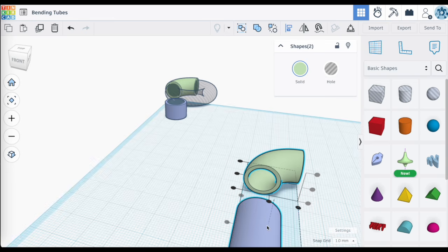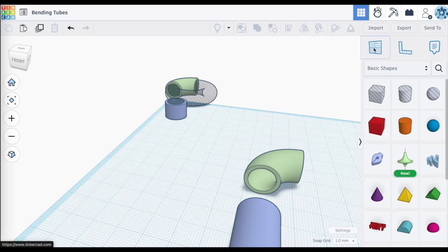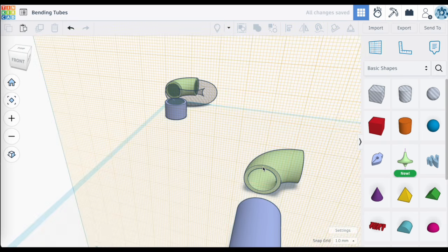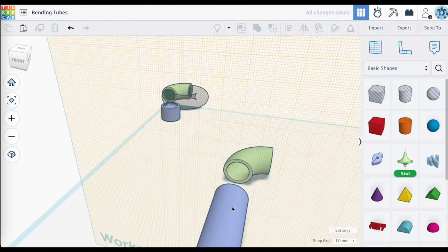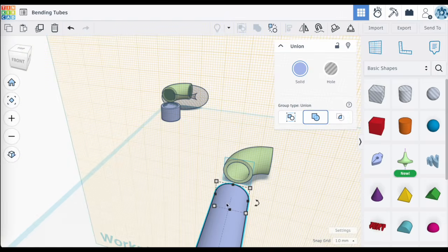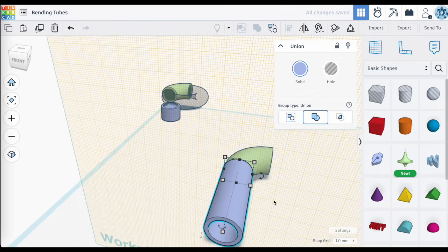Now, just to ensure that I can push this piece right up so it's sitting flush up against the opening there of my corner piece, I just use the work plane tool, drag this out, and just make sure that it is placed somewhere along that front facing surface. And I just select this now because it is aligned up perfectly in the other two axes. All I got to do now is just press D to drop to that work plane. Done.